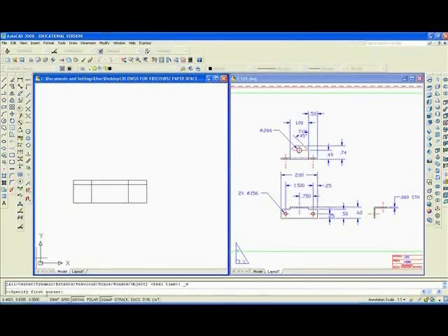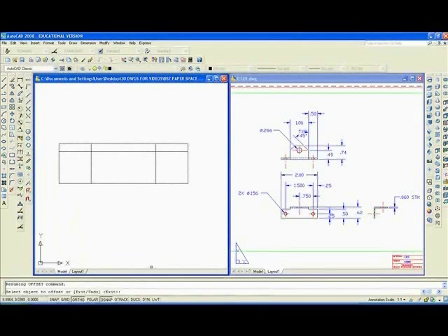Perhaps I'll zoom it to make it even larger. You'll want to type F, enter, hit escape, F, enter, radius R, enter, 0, enter. So with a fillet radius of 0, we can clean up these corners. I want to break this middle line, and you'll see why in a minute. Fillet again.